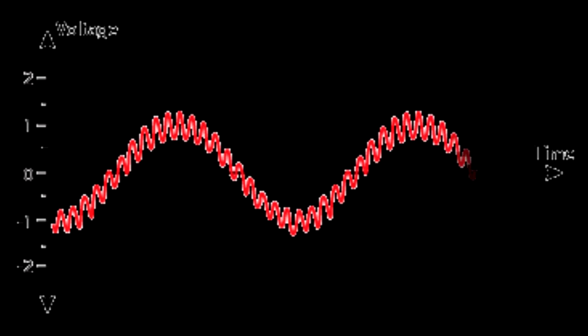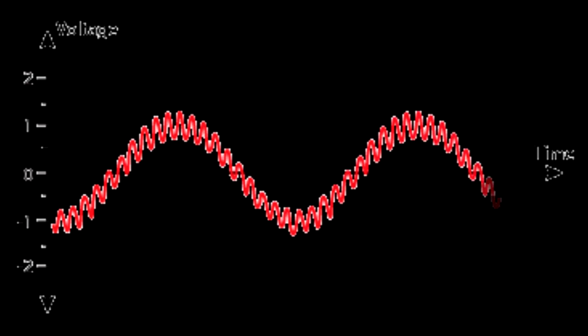As you can see in the graph in red, that is the raw data. When a low-pass filter is applied, it will keep the low frequencies and remove the high frequencies, which can be seen from the graph in blue. This is mostly used if there is a lot of noise in the data.